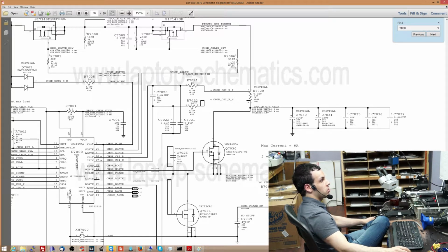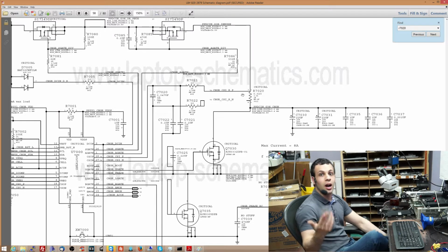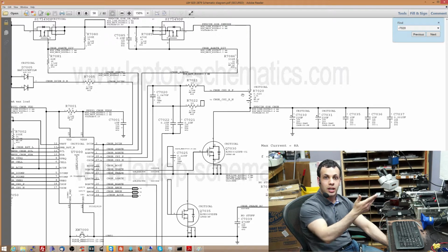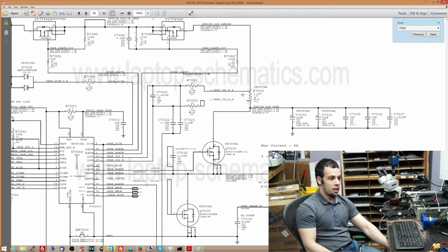Now, because that resistor dies, it reads nothing from one of the ends of this resistor. So it's going to think that there's a huge difference in voltage, which means it thinks it's using infinite amperage, which means, oh my God, I'm using too much power. Let me turn off the charger, when the computer is, let's say, on and using more power than it thinks it should be. Understanding how this works can help you understand certain problems.